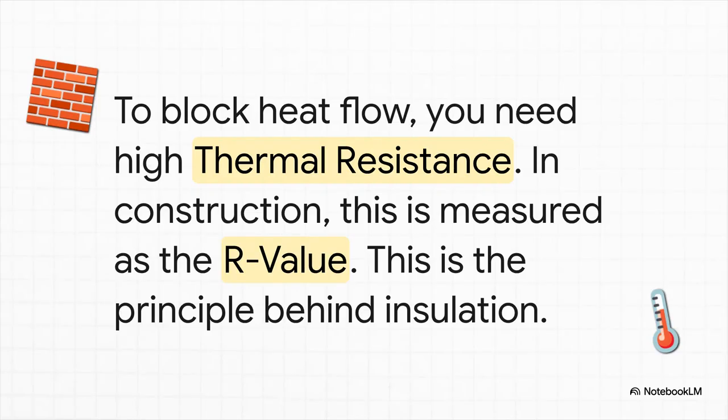And this brings us to a really practical takeaway. If you want to stop heat, you need a material with high thermal resistance. That is the entire job of insulation. You know the R value you see printed on insulation at the hardware store? That's it. That's just a measure of its thermal resistance. The higher the R value, the better it is at stopping conduction.